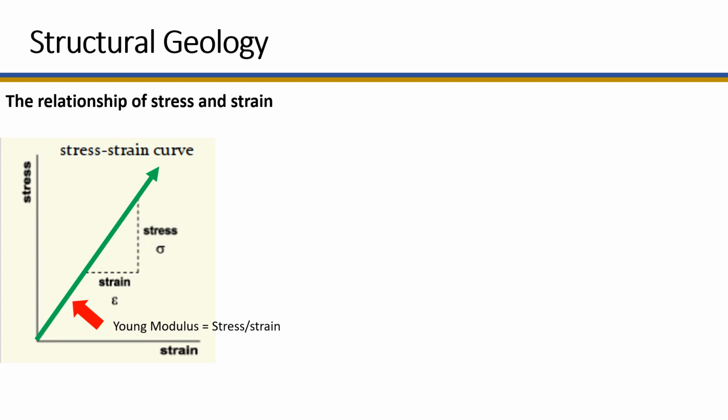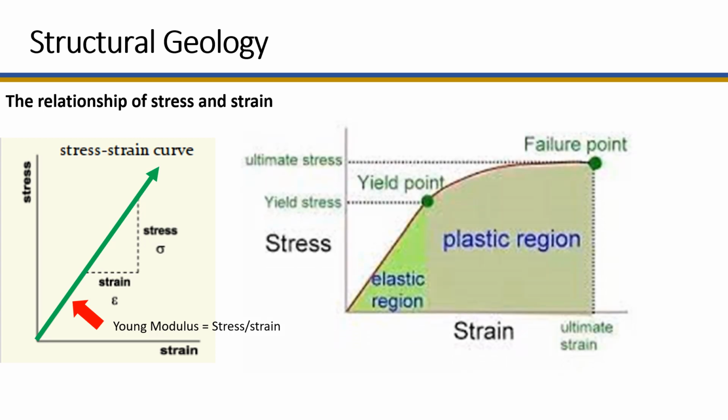Young's modulus depends on the material's physical properties and is determined through laboratory analysis involving various pressure and strain measurements. The resulting data is used to create a stress-strain relationship graph, and the slope of the best-fitting line represents the material's Young's modulus.